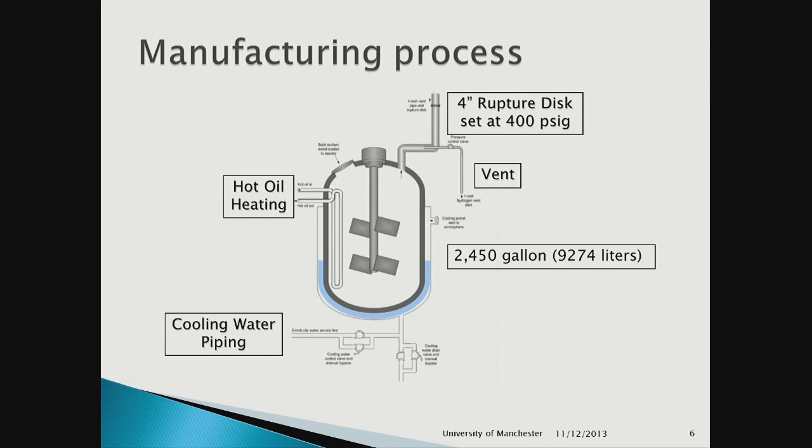It's got a capacity of 2,450 gallons, or about 10,000 litres. It's got a vent. It's got a 4-inch rupture disc set to 400 psi. So 400 psi G, we're 15. So that's about 20 bar.